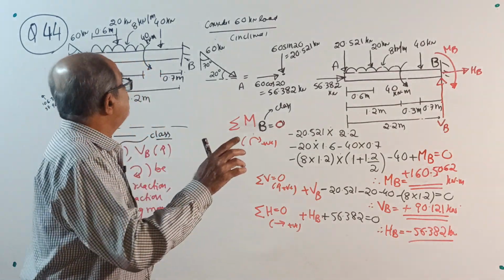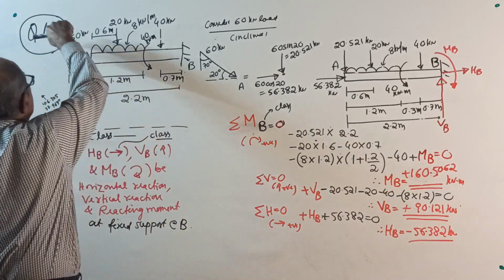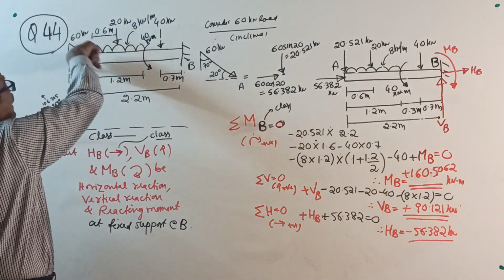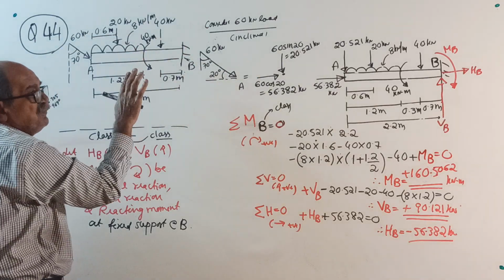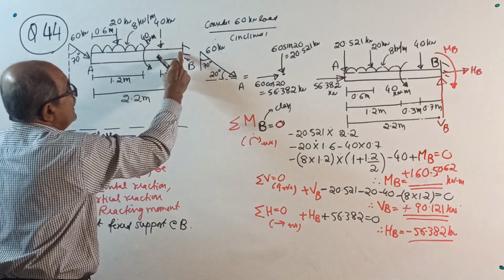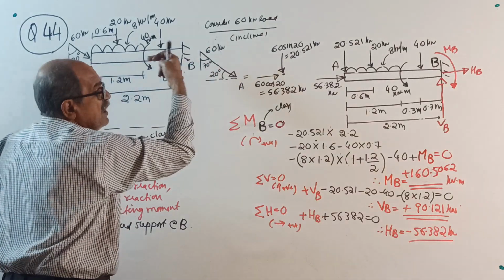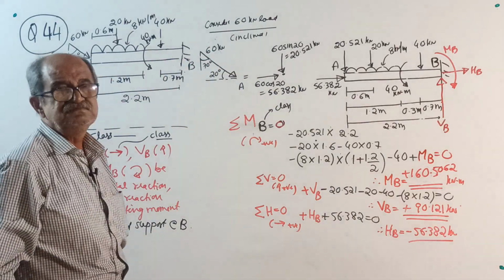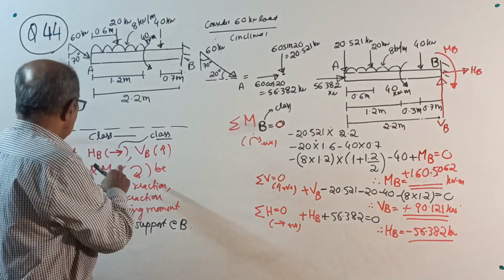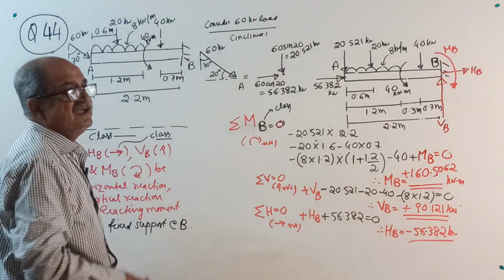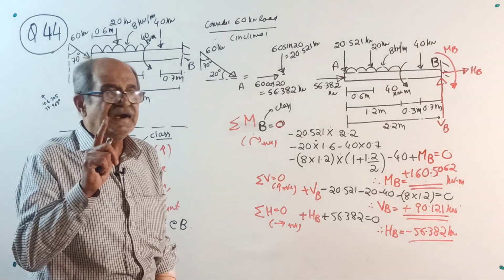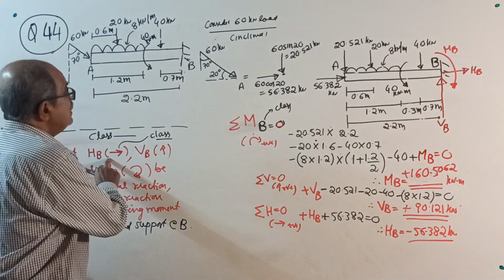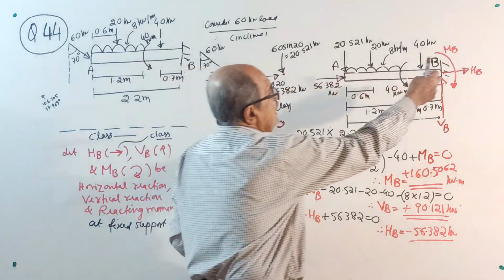Now, correctly observe here. This horizontal load has a horizontal component to the right side. There is no other force to balance it. So the horizontal force at B should be to the left side, guaranteed. But still someone will ask, why did you take right side? This is for those who can observe. If you correctly observe this HB in the beginning only, you can take left side.